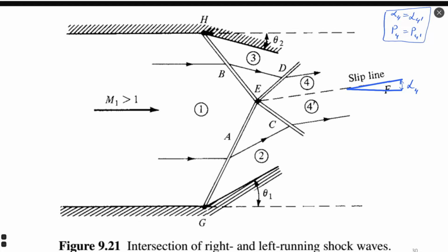Meanwhile, I will start to elaborate the model, or at least to explain you how this model is elaborated. We know that angle alpha or alpha 4, we can call it alpha just for simplicity because it's same for region 4 and region 4 prime. This angle alpha is caused by non-symmetric geometry, as I told you at the beginning. So we can assume initial value of alpha, we need because of iterative calculation. We need some starting value, and I propose here to use starting value of alpha for first iteration as theta 1 minus theta 2.